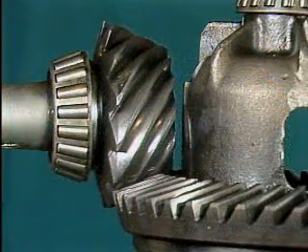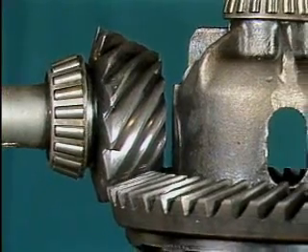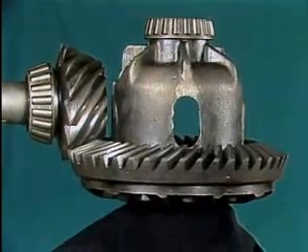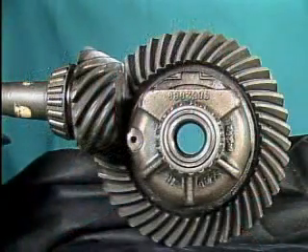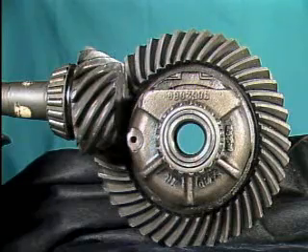This offset allows hypoid pinions to have as few as 5 teeth in a high-ratio gear set, while the various types of bevel gears typically don't have less than 10 teeth on a pinion. The smaller number of teeth on a hypoid pinion means that larger ratios can be obtained with a hypoid gear set than with a bevel gear set of the same dimensions. The gears we've looked at are some of the most common types of gears that are used, but keep in mind there are other types of gears as well.